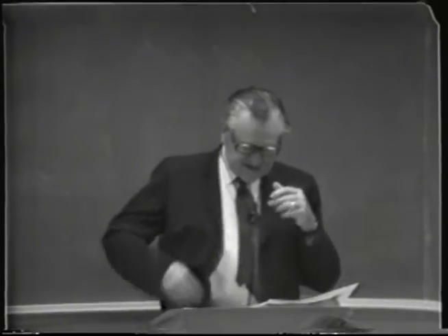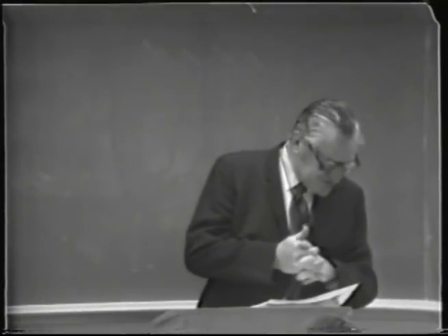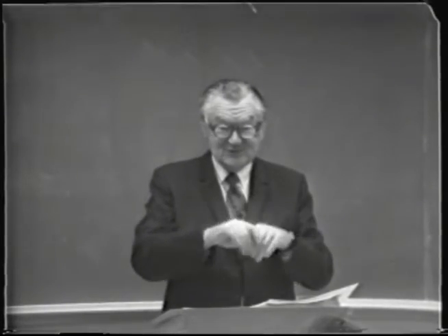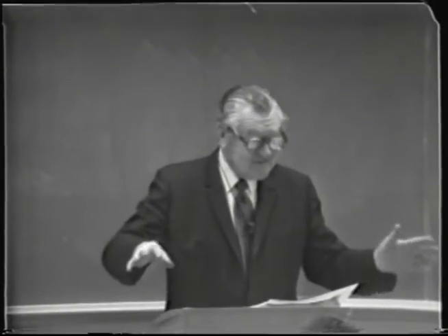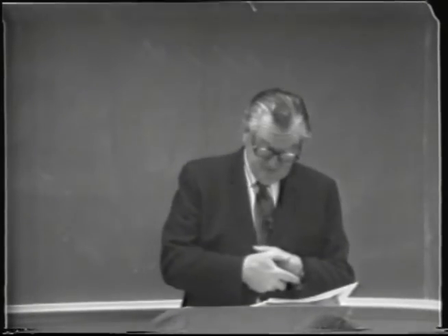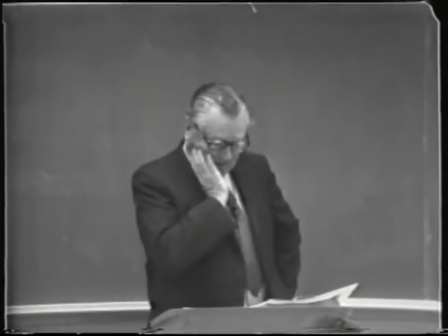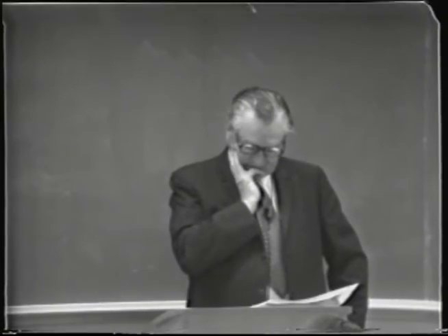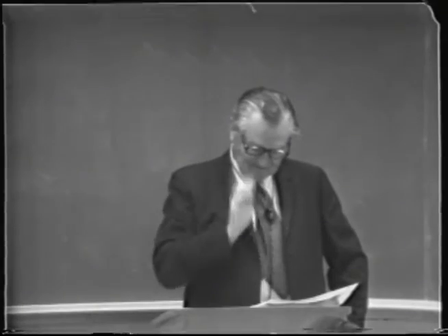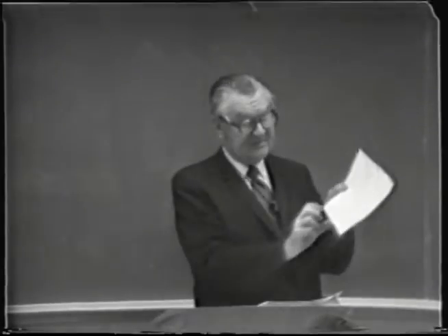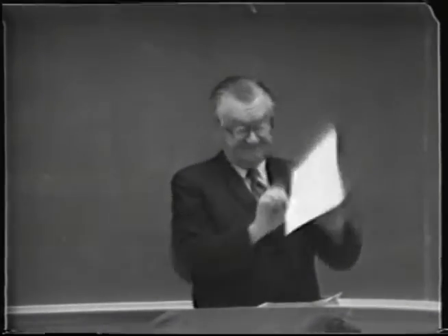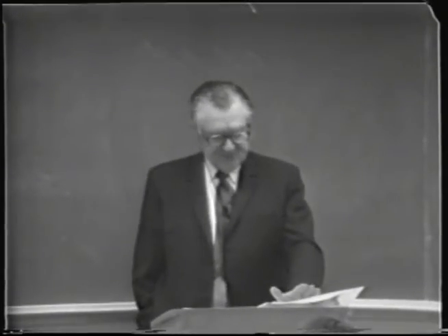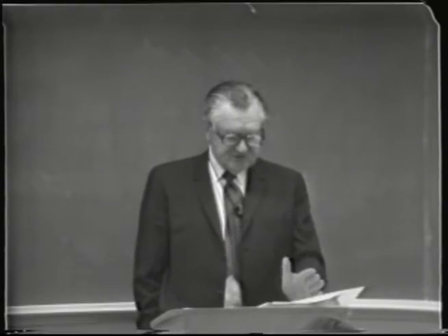See, the diffuser section is what we saw in that diagram I had out last time. And so that's where the confusion arose, is how that could create the suction necessary to pull vapor in. So anyway, that vapor at the low pressure P2, or the lowest pressure in the system, at the middle point here, is entrained and compressed to a higher pressure P3 at the expense of energy in the form of steam.